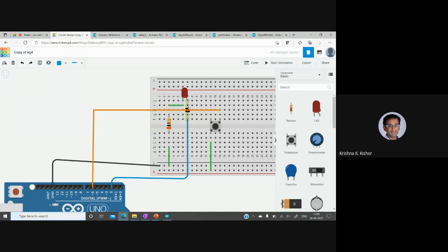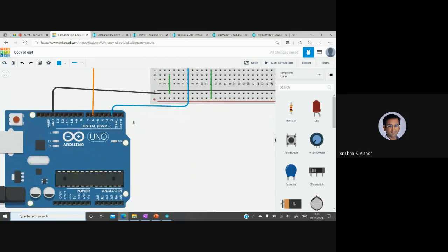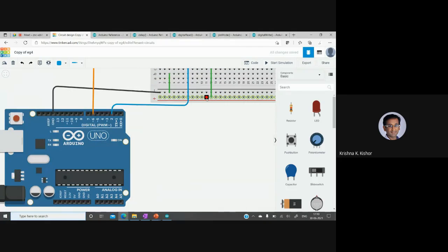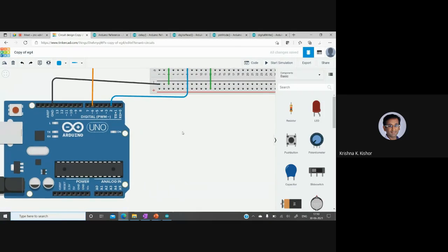So that voltage goes into the input of an LED, and then the usual circuit that you saw, right? It goes into the LED, comes out, goes to the resistor, comes back out, and it goes to the ground over here. Right. So now I hope that is clear. Right now, what we did remove was the power supply line for this one. So let's connect a wire to it. We'll connect a 5 volt line.